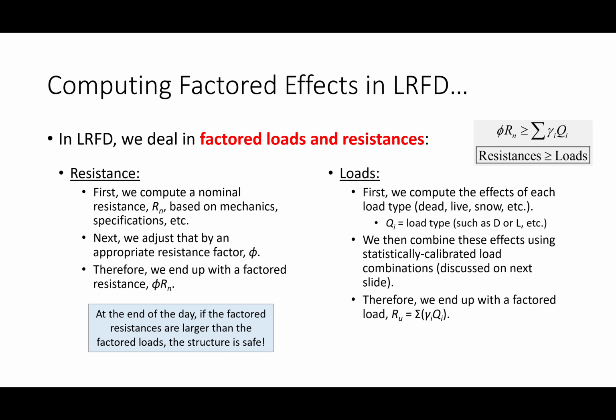So resistance factors are usually 1 or smaller than 1 because they're decreasing the resistance. For the most part, load factors are usually bigger than 1 because they're amplifying the loads. So we combine both of these effects, but at the end of the day, as long as the resistances are greater than or equal to the loads, the structure's fine. This is a high-level view of what we're going to be doing the entire semester. So if even now this is a little fuzzy, don't worry, we're going to get a lot of practice on this. It won't be that bad. All right. Sound good? Okay.